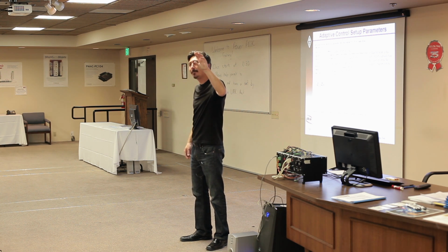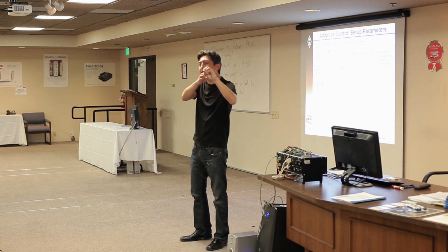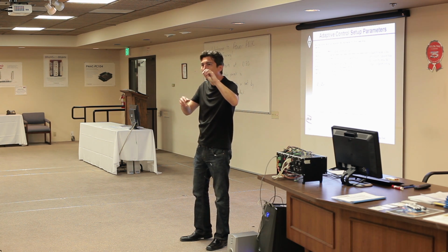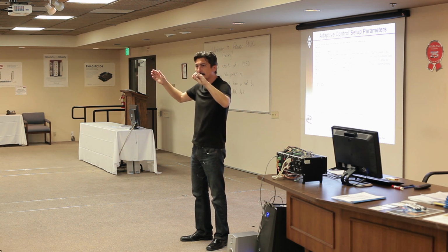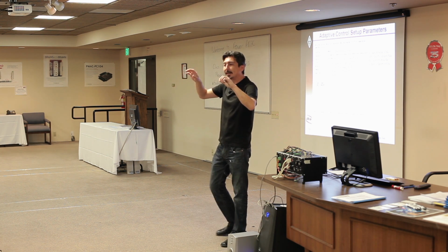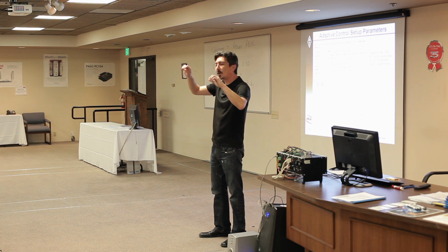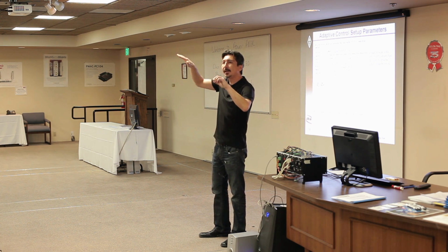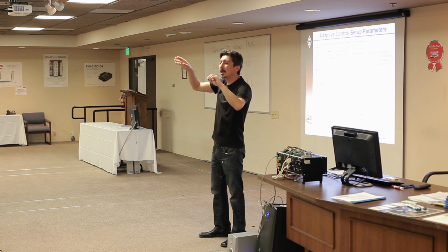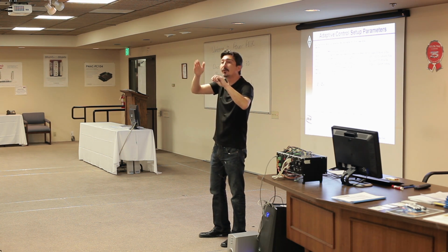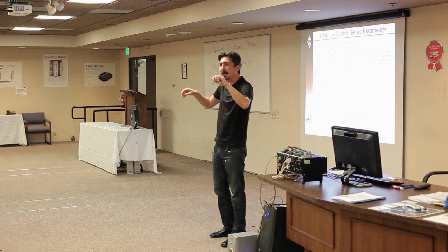So, okay, at max inertia, let's say, I want 10 hertz bandwidth. With really low inertia, where your gain is high, I want like 40 hertz bandwidth, with some damping ratio. Still, it's going to be similar. The estimation algorithm is going to be the same. But what I do is I change linearly when the gain changes. Let's say if I'm at nominal gain, then the bandwidth is going to be around, let's say, 25 hertz. So it's going to basically linearly change the bandwidth and the damping ratios around these values.